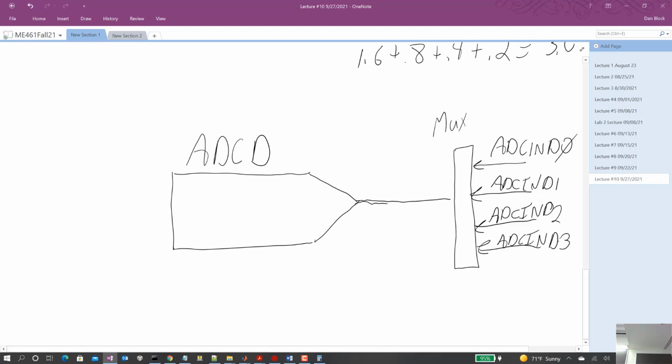But for now, just think about, okay, so we got some voltage coming in. It's a sine wave, moving voltage, or it could be, like you're going to use in lab, a little potentiometer joystick. And as you move that joystick, a different voltage is coming into the ADC pin. Or we're also going to use in lab, not on these D pins, but on I think B, our microphone signal. When we whistle, there's a sine wave. Or when we're just talking, it's the crazy looking voltage changes. You've seen that on an oscilloscope before, or in a movie, where you see your voice going across. Anyway, those can get sequenced into the ADC.